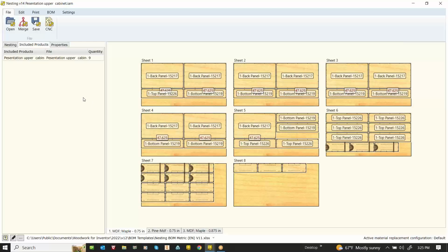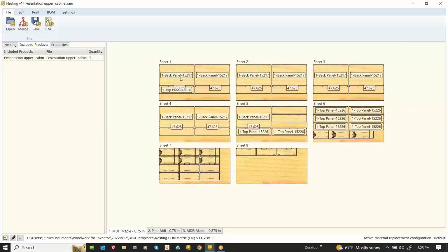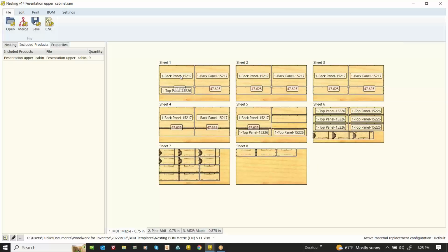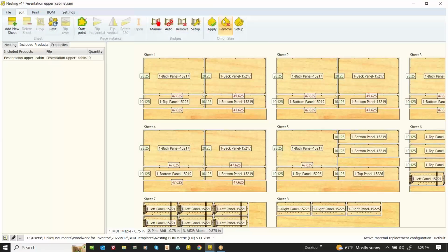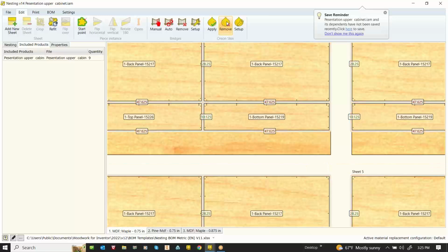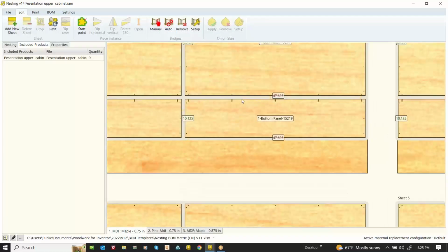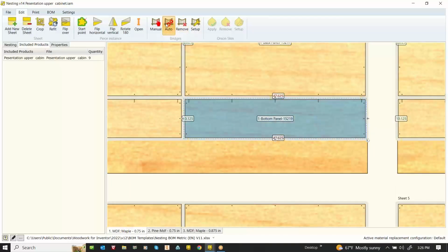If I now wanted to do certain things, for example, if I wanted to put onion skin on this, you could have done it previously, or you can go into apply onion skin, apply. And you could see that I've applied onion skin to every board here. Remove. Or I can do bridges, auto. And if we take a look at this, let me just highlight one of them. Auto. Bridges now become available, and remove them. So again, just real simple things.